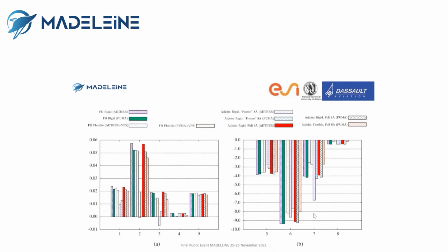We have 9 variables in this case: 4 twist angles plus the rotation angle of HTP, variable 9, and variable 5 to hide the camber parameter, and we compare both results obtained using finite differences and adjoint, with and without gradient of turbulence, and with and without flexibility effect. I will explain what I have in mind with flexibility effect.